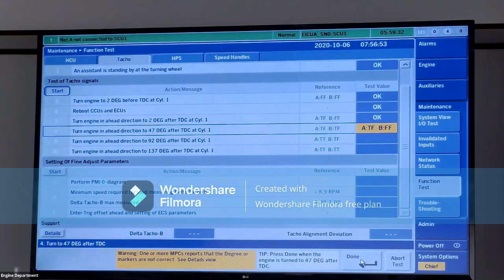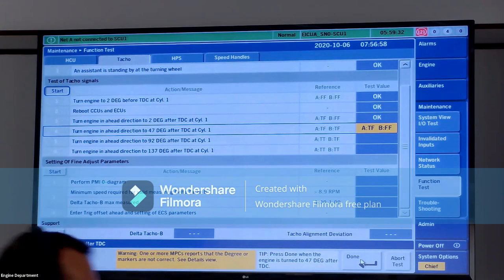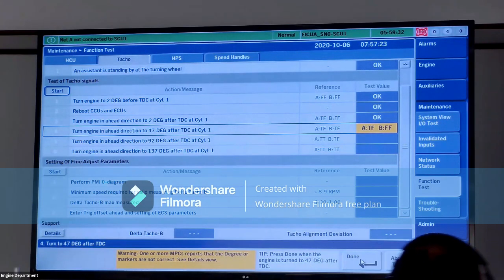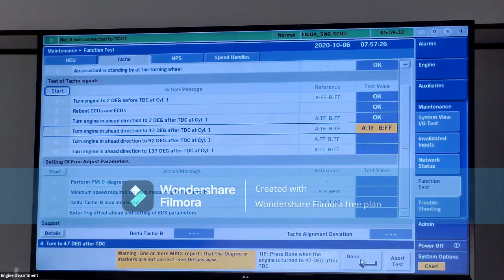So it will be required to adjust the encoder B again. Put the crankshaft position at 45 degrees, loosen the clamping ring of the encoder B, and adjust the encoder B in such a way that the marker master B LED of the amplifier B switches on exactly at the crankshaft position of 45. So we are adjusting, turning the hollow shaft until the LED comes on.